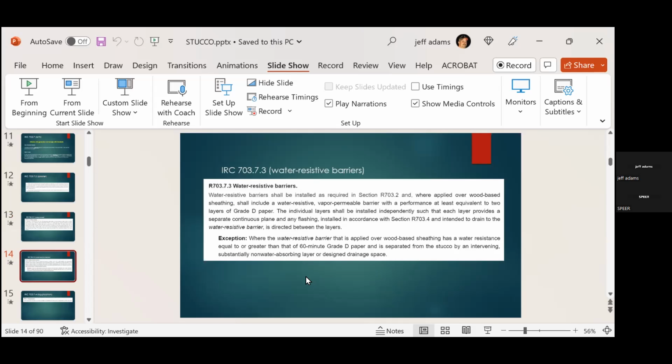The stucco or the plaster is water resistant. It's not waterproof. It is really there to be water resistant, to be a decorative detail to the exterior of the house, and then to protect these WRBs from impact and from UV damage, because all these products have an issue with overexposure to UV, especially on your bigger houses. It creates a massive problem.